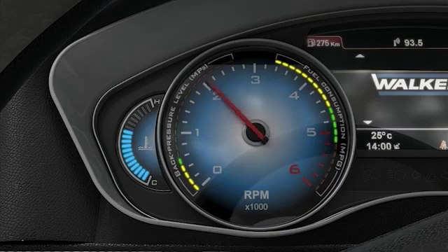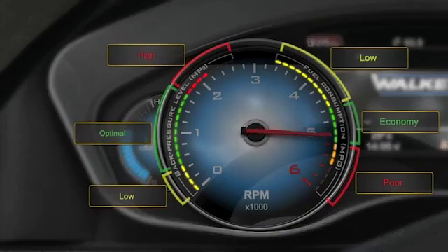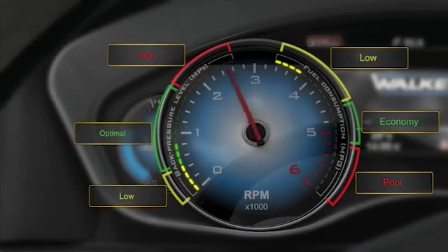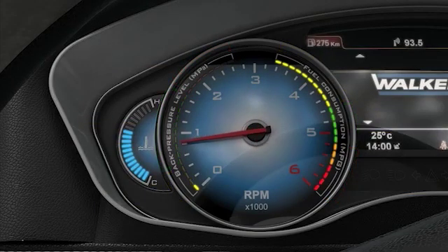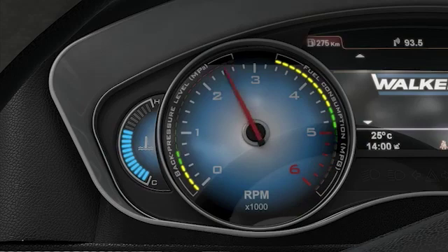It is easy to see that in a conventional exhaust system, the level of back pressure is directly proportional to the amount of gases flowing through it, i.e., when the number of revolutions increases or decreases, so will the exhaust system's level of back pressure.